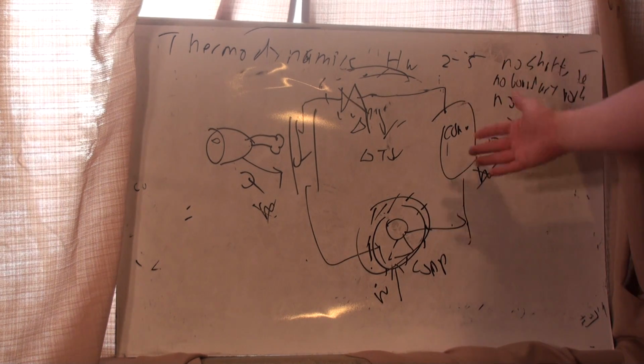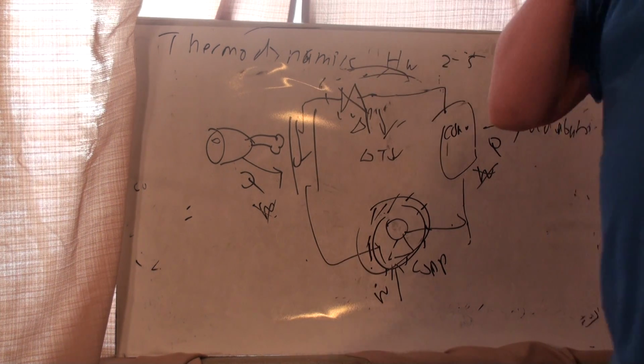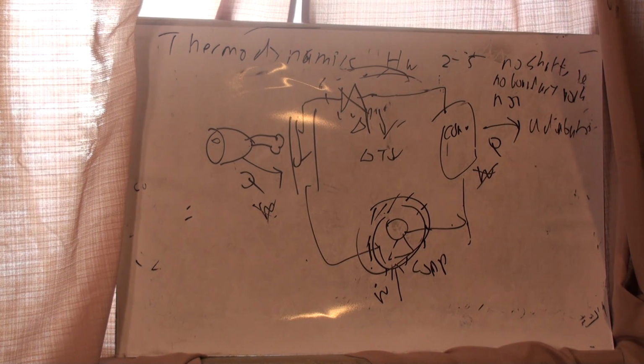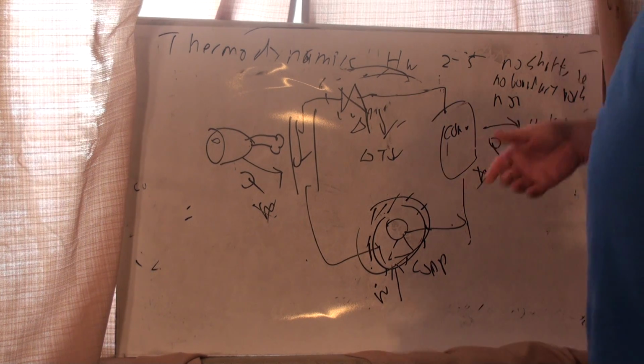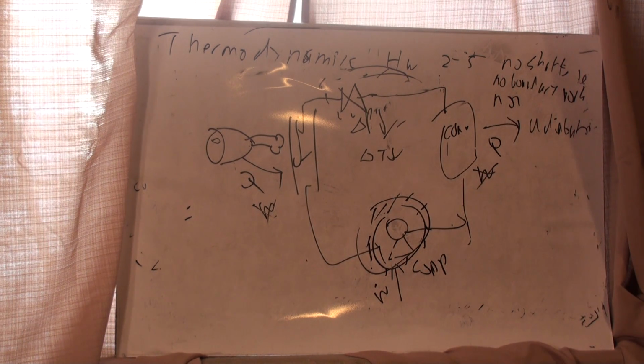Okay. Here, there's no work, there's no boundaries again, so this is just heat transfer. And here, again, there's nothing going on. It's just going through an expanding valve. Okay. So there's no work, but it's also adiabatic because it's so fast. Okay. It doesn't stay at the same temperature. It cools off rapidly. Think about those air canisters that you use to clean your computer. Well, what happens? It gets cold, right? Because you have a sudden expansion of this liquid into a gas. So that's kind of what's happening here, yeah, essentially.